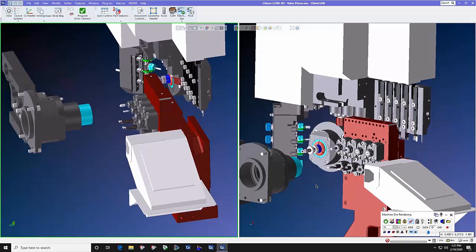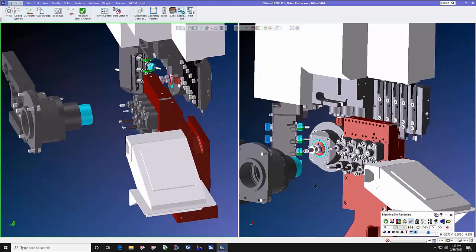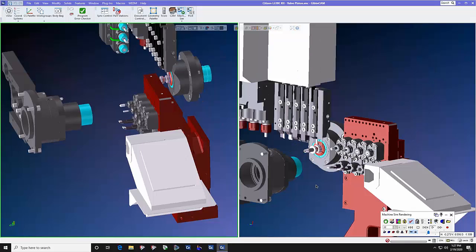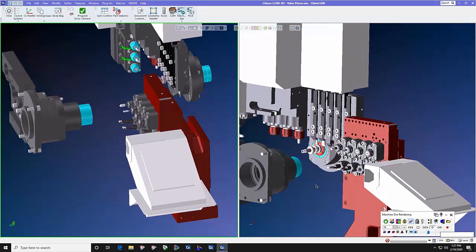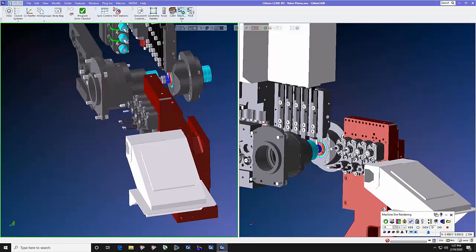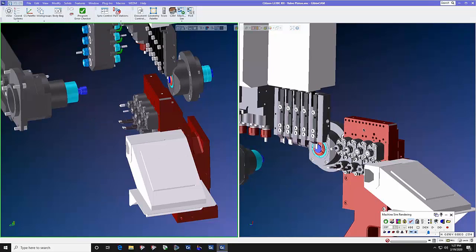Solids are not required for MTM, but they are highly recommended because, as we demonstrated in this webinar, there's a lot more going on than just the interactions between the tool and the part. Here in this Swiss machine, you can see that we have tool holders, spindles, collet nuts, nuts and bolts and screws and parts catchers, and those are the kind of things that we need to show solids. And again, GibbsCAM will deliver to you a machine-ready package, and all you do is plug in your tool paths and your tools, and you're ready to go.